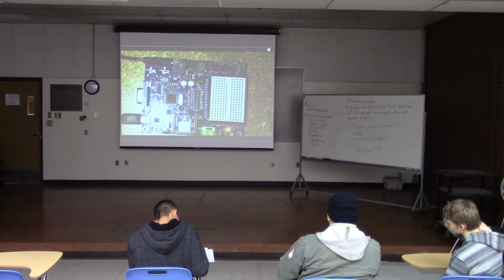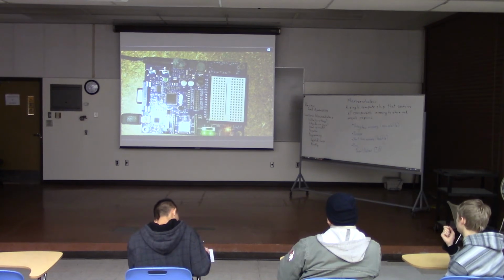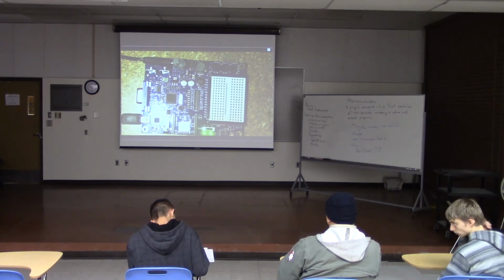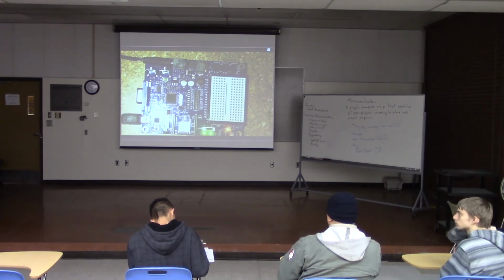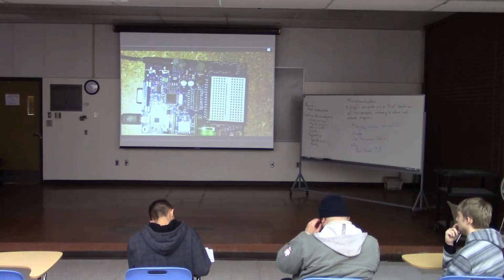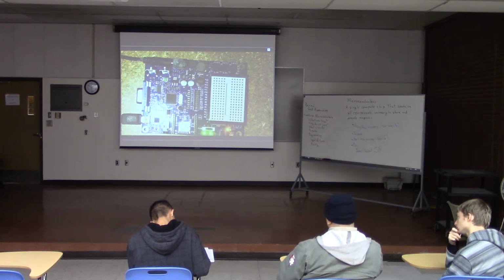So what's happening is that there's something called a voltage regulator on here. Basically, the computer chip likes to have a very fixed, very constant voltage. So we don't want to have it hooked up to a battery where the voltage starts out high and then drifts down slowly as the power is used up. We want to have it hooked up to something that creates a very constant voltage. So that's what a voltage regulator does. It takes one voltage, which might shift around a little bit, and brings it down to a lower voltage, which is always constant and always steady.